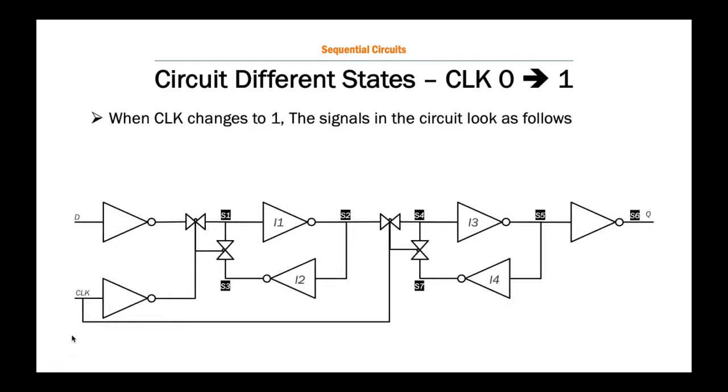So here's my circuit again. What I'm saying is that my clock is going from 0 to 1. So I would imagine 1 is going to be here, 0 there. So that door is going to be closed. So that gate is going to be shut. And then since this 1 becomes 0 and then gets inverted again, this one is open. So that gate is connected. Similarly, that clock, which is 1, is going to cause this gate to be open, connected, and this one to be closed. Closed means shut, okay?